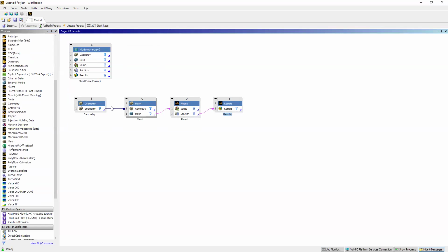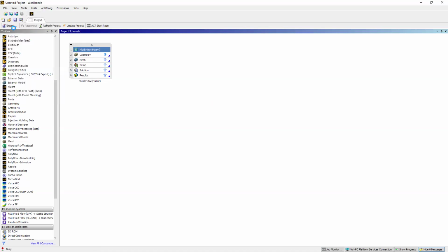Geometry is done in the Design Modeler. Meshing is done in the Workbench meshing or ANSYS meshing. And we can post-process the results in CFD Post, but we're not going to do that. So I'm going to delete all these things and we work on the case here. Select them all and press the delete key from the keyboard, like any Windows command. Okay, and save your project file.